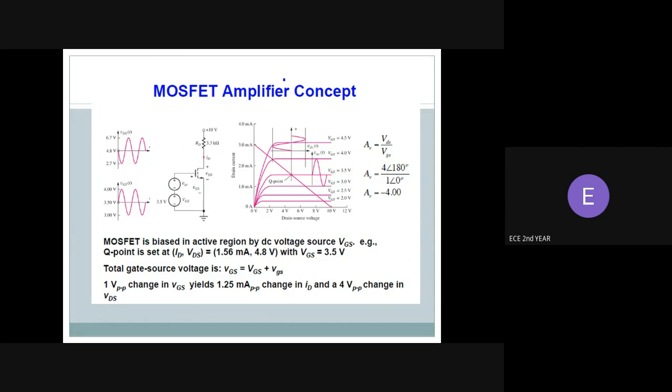Enhancement MOSFET, or E-MOSFET, is classified as a normally-off device that only conducts when a suitable gate-to-source voltage is applied, unlike depletion MOSFETs, which are normally-on devices conducting when the gate voltage is zero. However, due to the construction of the enhancement type of MOSFET, there is a minimum gate-source voltage called the threshold voltage. That is, there must be a gate voltage before it starts conducting, allowing the drain